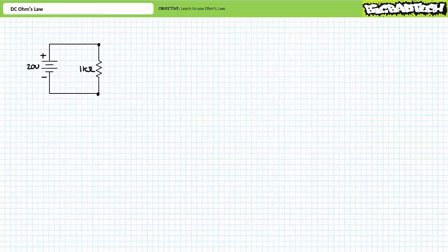You don't need a $50 flowchart to tell you this, and it's not like Ohm's Law is some magic secret. At its heart, your understanding of Ohm's Law quickly and efficiently cuts out a whole lot of dead ends and useless busy work. Determining why the voltage is too high, why the resistance is too low, or both is the next step in troubleshooting. This is where an intimate understanding of how a system is intended to operate comes into play. It is my intention not to roll out a flowchart that shows you how to troubleshoot a single system, but rather arm you with sufficient technical knowledge to understand and thus troubleshoot any system.